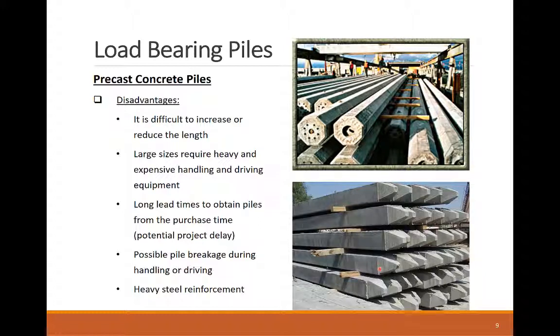However, precast piles come with fabrication and installation challenges. Similar to timber piles, it's difficult to extend the length of the pile after it's fabricated and delivered to the site. For higher load capacities, precast piles don't become the most feasible option due to their heavy weights and increased need for large cranes to handle and drive them. These piles are fabricated off-site, so there is a lengthy process of shop drawings and submittal approvals that extend their lead time compared to other pile types.